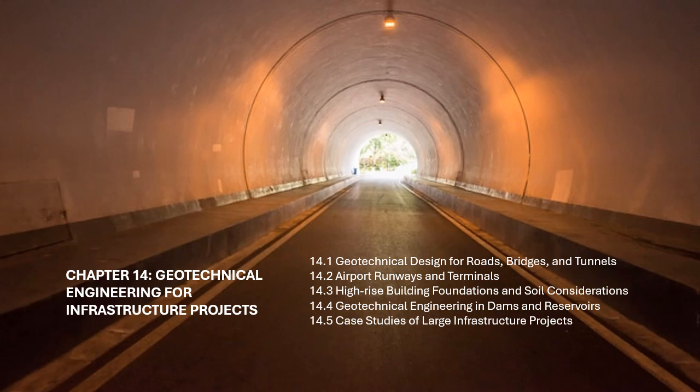Hoover Dam, USA. The Hoover Dam, located on the Colorado River, was built on a foundation of hard limestone and granite. Geotechnical engineers carefully assessed the rock mass conditions to ensure that the dam would remain stable under the immense water pressure. The dam's design incorporated a complex drainage system to control seepage and prevent water from weakening the foundation.